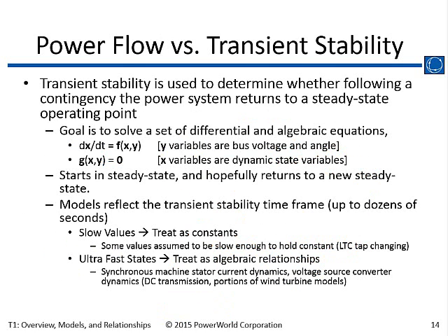Okay, so what we do in transient stability is we actually are still solving a set of equations that are close to the power flow equations. We call them the network power balance equations. They enforce the algebraic constraint that says, hey, at every node in the system, the P coming in has to balance out. We treat the whole system as a coupled set of algebraic constraints.